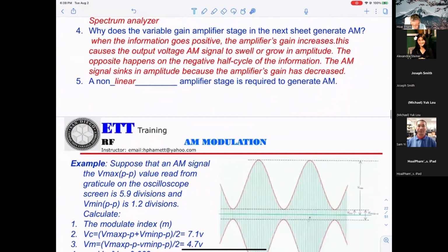If you see the carrier right here, that means it is just a constant frequency, no changing at all. However, when both combine in the modulator, you can see your voice on this side, and this signal here is the carrier. The carrier will be changed with the amplitude of your voice. And this is what they call the envelope.